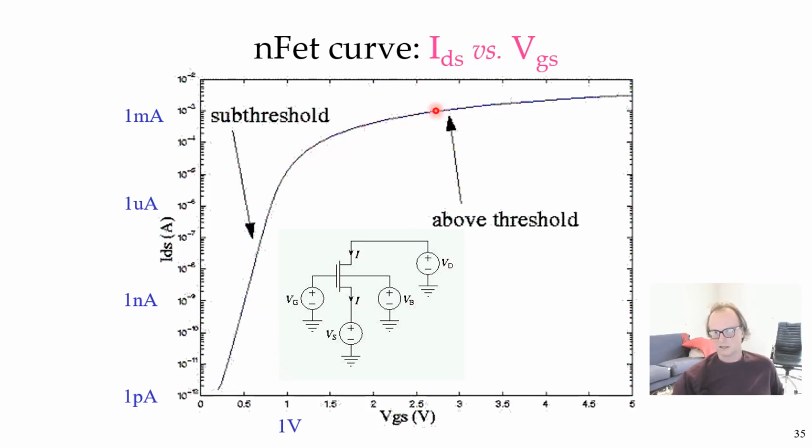And if you measure this, you'll see this is actually square law behavior. But square law behavior on an exponential scale looks almost flat. It just doesn't increase that fast. So that's what you guys are going to measure. Your mission should be to measure a curve like this. Of course, you'll have less dynamic range because the current to frequency circuit that you use has much less dynamic range than the source measure units that we used in the past, the Keithley source measure units. But you'll be able to get some parts of this curve.